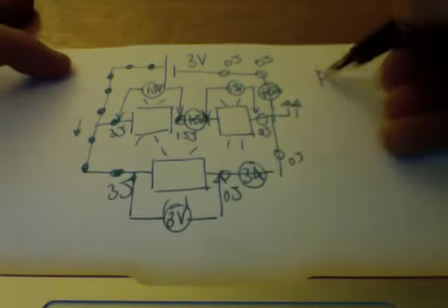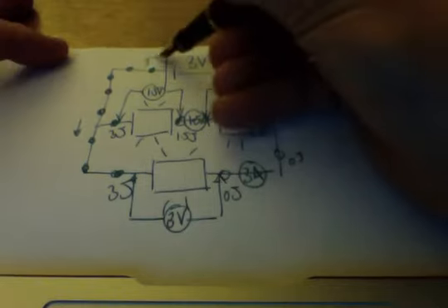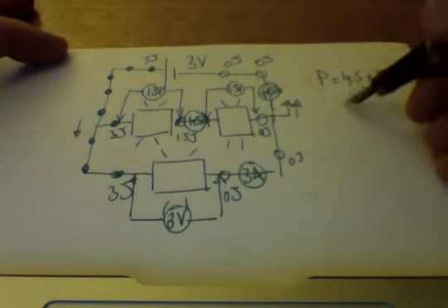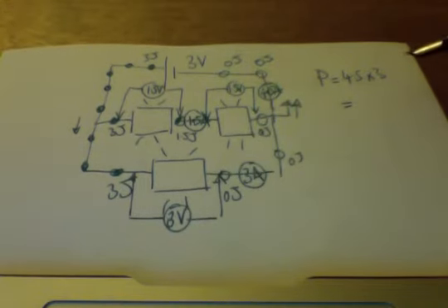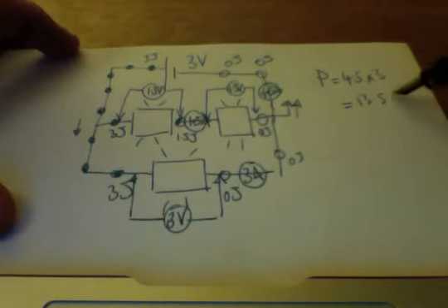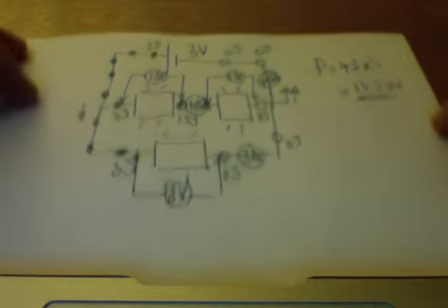Okay, if we just look at the power as well, I've got 4.5 coulombs per second coming out. Each one's carrying 3 joules, so 4.5 times 3 should give me, I'm going to have to do that quickly in my head, 12 by 1.5, 13.5 watts. Maybe you would like to try the next example. So if you want to, you can hit pause after I've drawn the diagram for you.